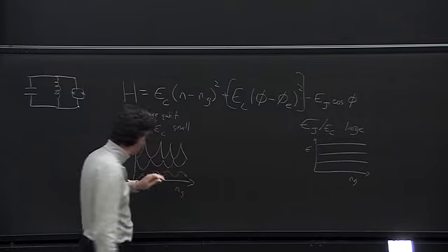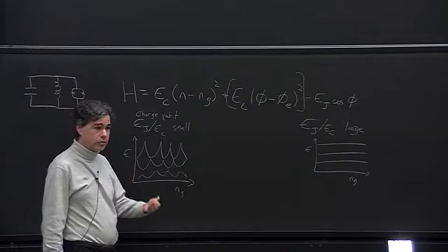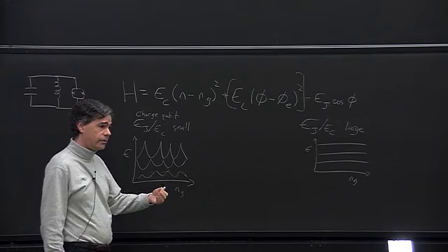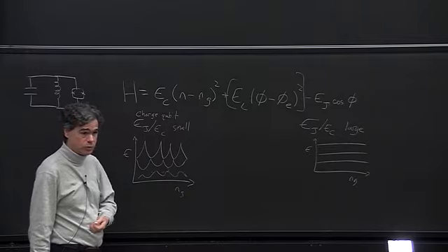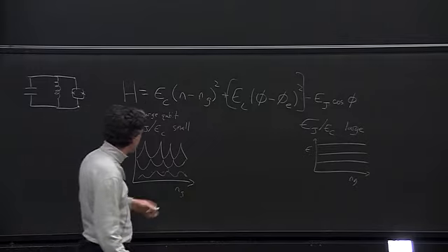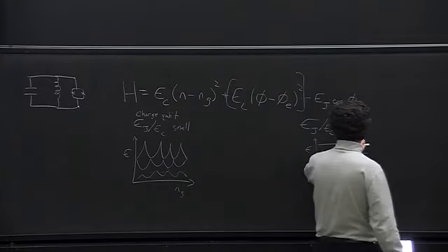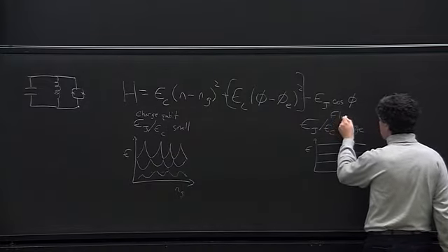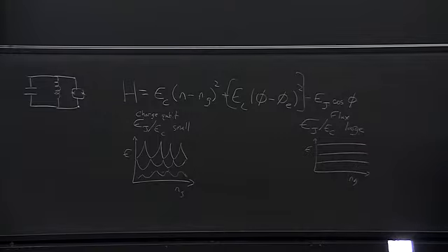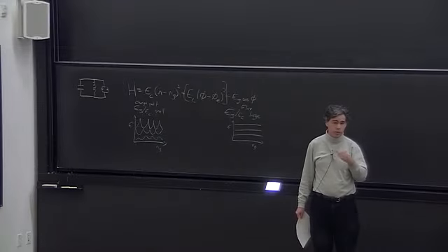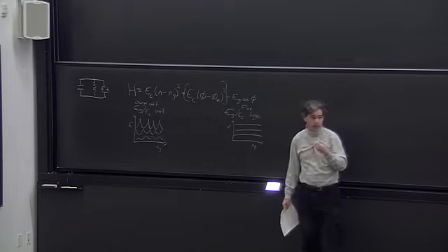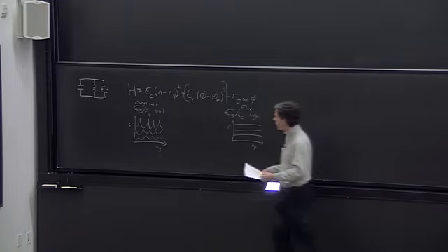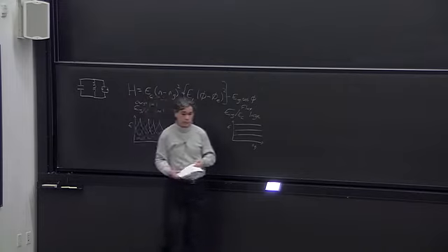Because basically what this boils down to is saying that your qubit is stored in whether you have, say, an extra qubit pair here or here. And that's the difference between the 0 and the 1, roughly speaking. And over here in the range where this is very large, this is called the flux qubit, because the thing that determines the value of the qubit is more about the superconducting phase. And that's controlled by the flux, the magnetic flux, through, say, this little Cooper pair box. Okay?